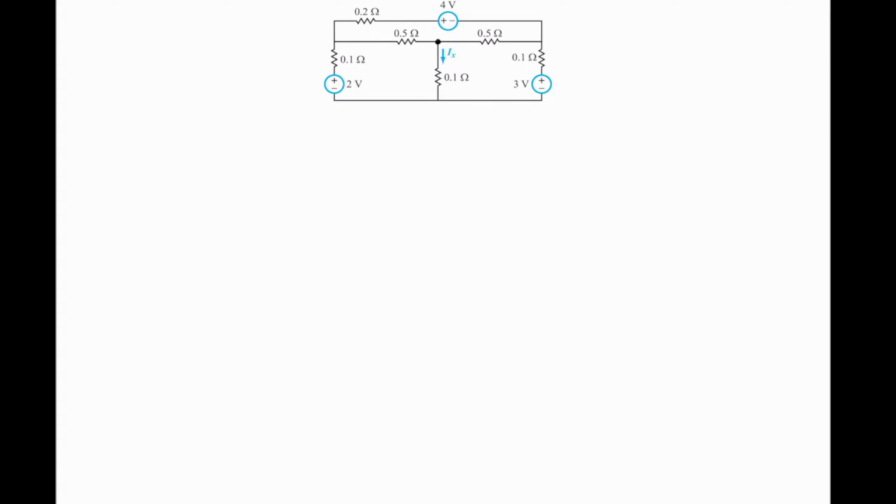We can call that V1, but note that we have some voltage sources in the circuit causing there to be voltages at these 2 points. We would want to know those voltages in order to know the voltage above Ix. So we can start from the left and say this is V1. Above Ix, that's V2, and we can call that V3. We put our ground, because we take voltage with reference to ground if there's no voltage source, and we call ground 0.